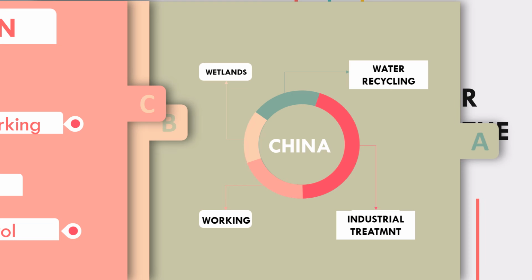The combination of two or more types of constructed wetland system is called a hybrid constructed wetland system. Selection of constructed wetland system depends mainly on the target element for treatment. Constructed wetlands are mechanically simple but biologically complex systems.